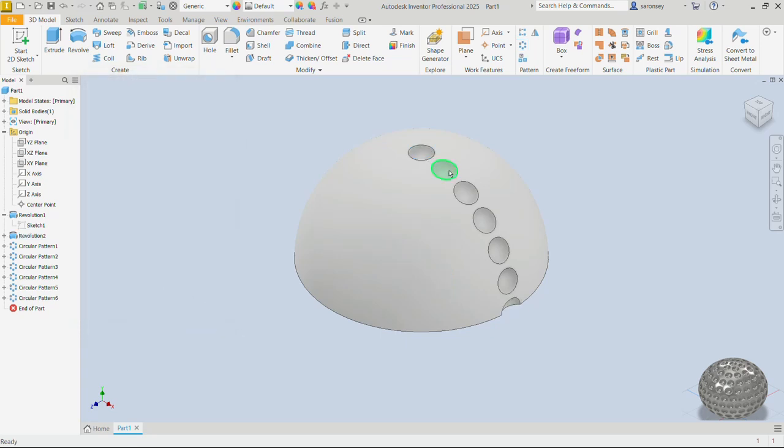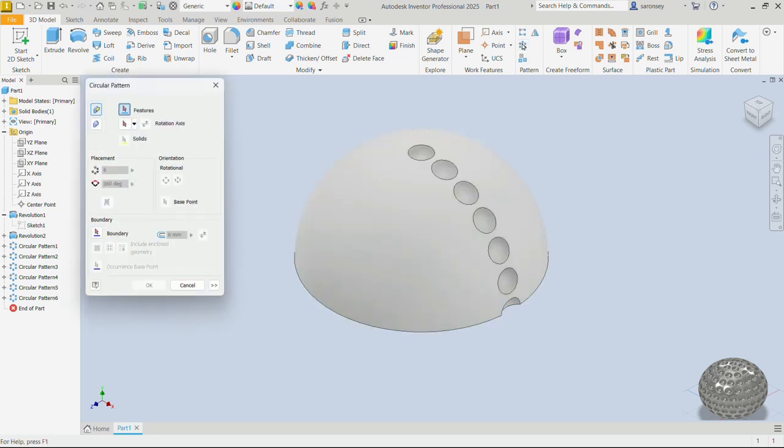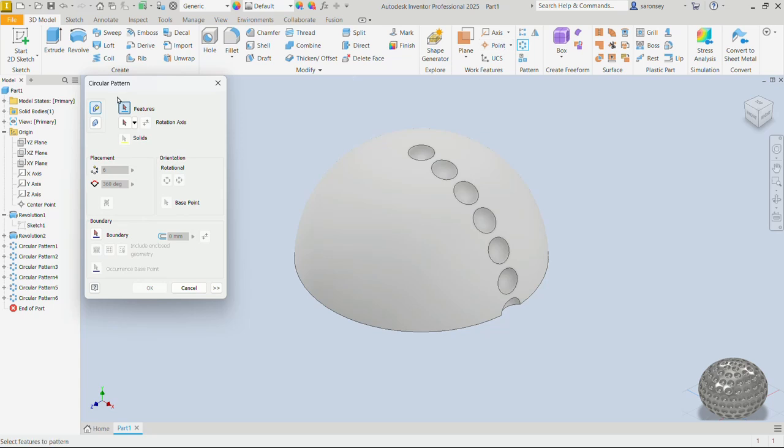So like I mentioned, now we want to circular pattern these individual dimples around. They would all have different occurrences. That's why we had to pattern them individually. Now let's see, we'll pick the circular pattern command. Now the feature we want to pattern is going to be the second one. When you select it, it would select the first one in addition because it is a circular pattern of that. So don't be so alarmed.